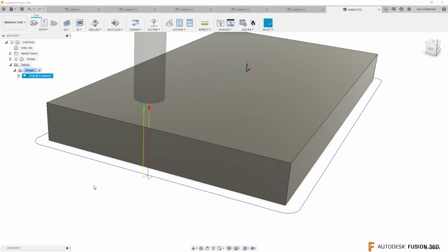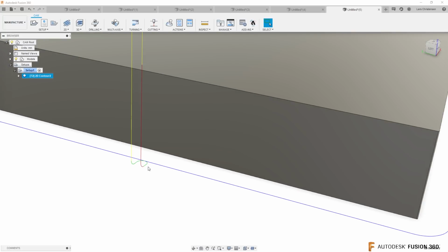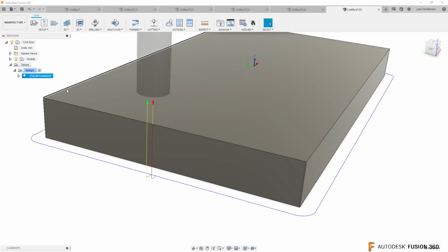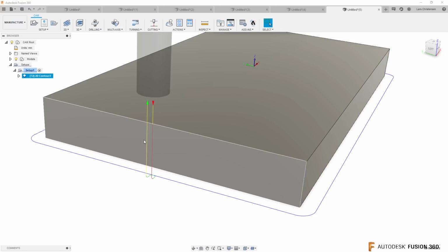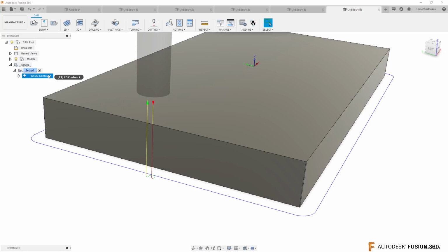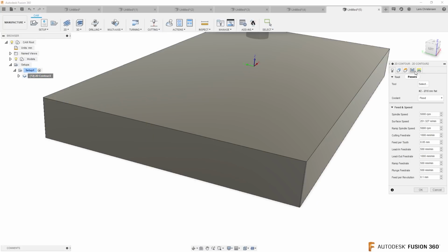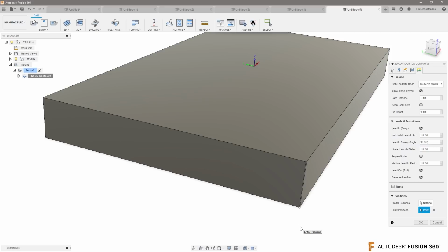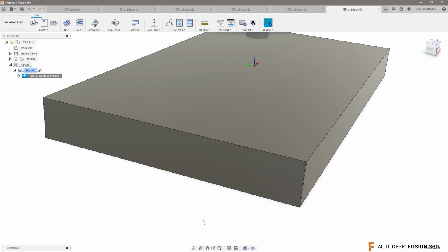What many times happens is that the cutter comes in and it's cutting a lot of material, and the servo motor on your mill comes in and has to do this arc, and it sucks the cutter in a little bit. What I have done to solve this problem is I would never start on the face, because I hated machining a piece of steel and having that little sucking mark in the center. So what I always have done is right click on your operation, go to the last tab, and down here you can change an entry point. Last tab all the way in the bottom, and just select that edge right there, or that point right there, and hit OK.